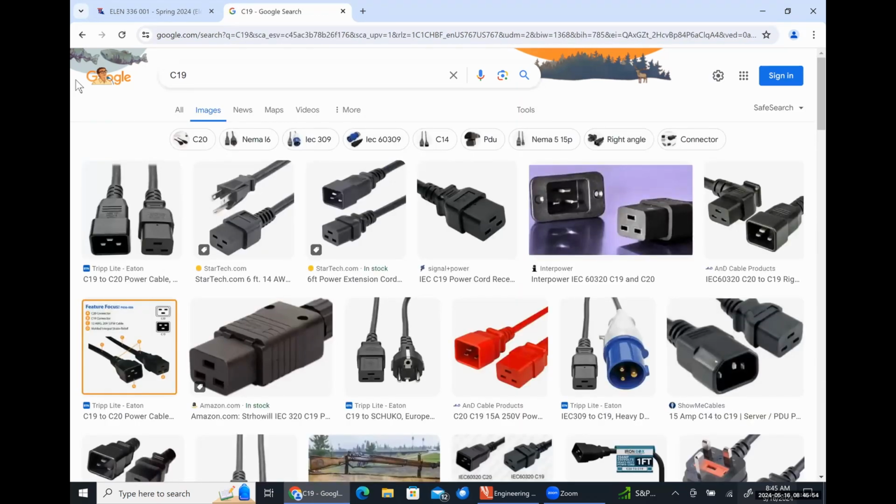Yeah. Well, I've heard some people say that when you go to Europe, you have to be very mindful of your phone or power supply. Most chargers for laptops or cell phones, if you read the fine print, are rated for 100 to 240 volts AC, 50 to 60 hertz. So they'll work in Europe, but you need an adapter because the plug configuration is different.